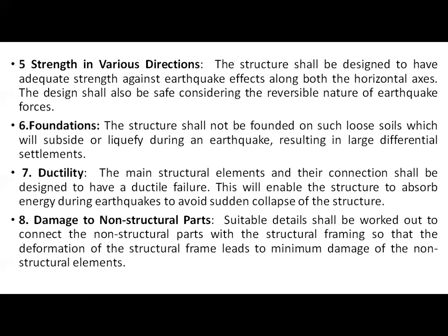So for that purpose, we should make sure that the structure shall not be founded on such loose soil which will subside or liquefy during an earthquake and result in a large differential settlement. This is the first point, about liquefaction. The second point is, look, resulting in a large differential settlement.